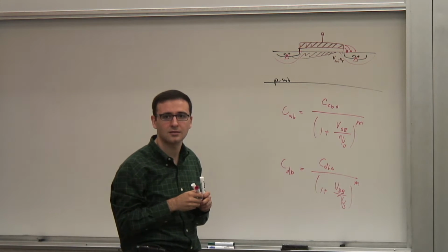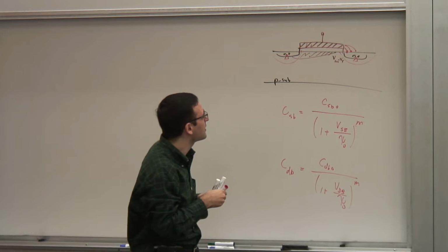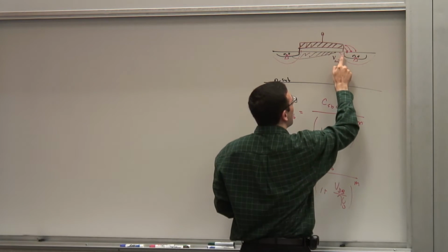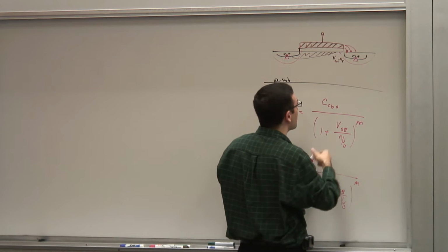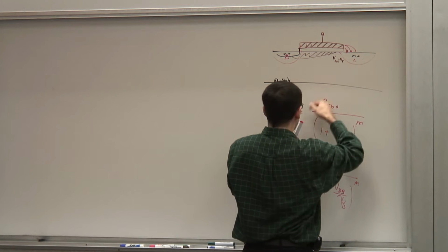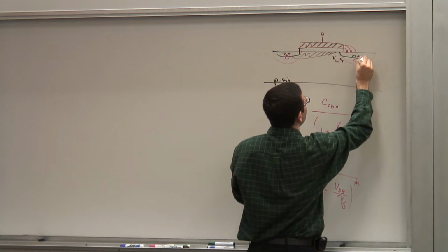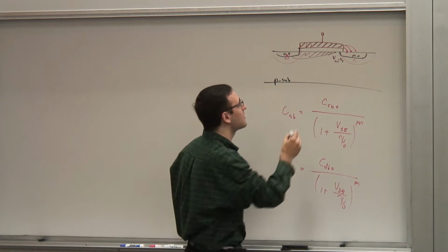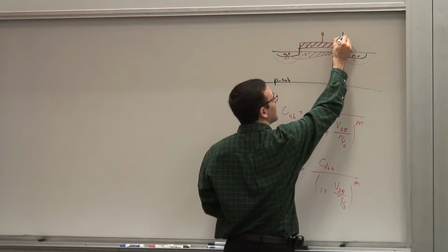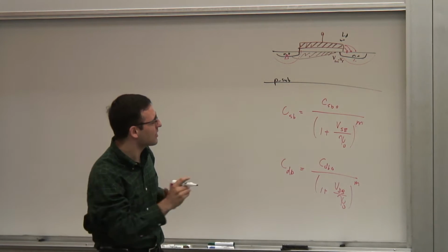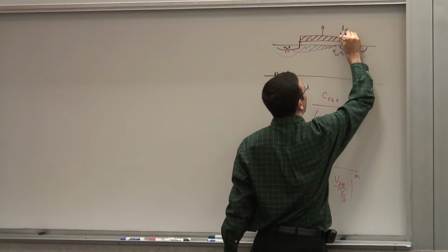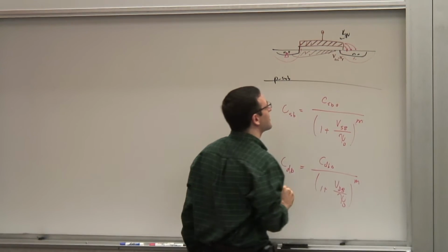Like that. And more importantly, actually what happens is that when the way you build these things, in the thermal cycles you put them through, usually the drain and source are extended a little bit underneath the gate. There's a little bit of overlap here. Let's call this length LD, the L overlap, for this capacitance.